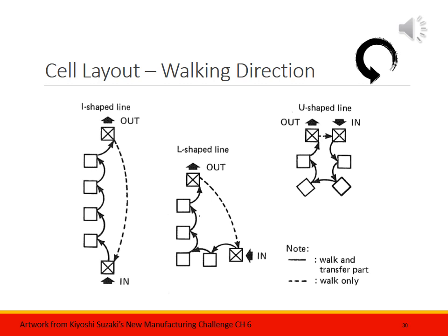And when your Kanban is full and your finished goods inventory is full, and you're not getting pull signals anymore, your pacing operation, the pitch of the cell based on pallet pulls, has gone quiet, then you can have one person in the line run as needed, maybe 2 hours a day to fill the finished goods inventory. That's why you want to have a U-shaped cell. So you can have 1, 2, or 3 people in that cell.